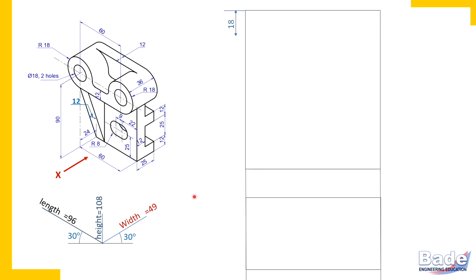Okay. Now we'll start constructing shape part by part. So there are two cylinders I can see here which are connected by plates. So two cylinders at top, from front, this is front direction. That means in front view, these two cylinders will appear. These are hollow cylinders. So locate center. From top at distance 18 millimeter, that is the radius of the object, this center line which is parallel to length. So I am drawing that center line. This center line is parallel to length axis. Length appears horizontal in the front view. So from top, measure 18 millimeters, that is center is at distance 18 millimeter from top, and then draw the center line.